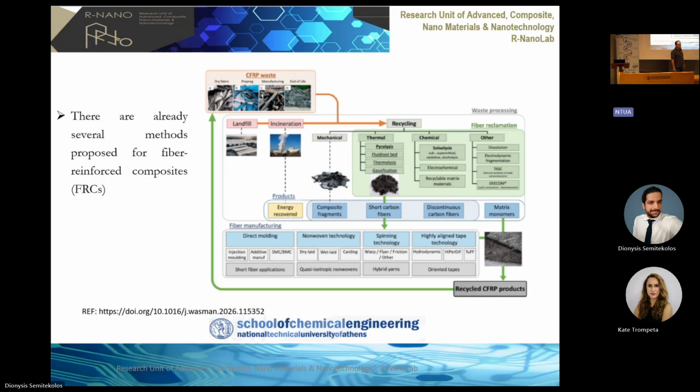Among thermal methods, the most well known is pyrolysis. When you have pyrolysis, what you do is burn out the organic material, which is the matrix, and you are left with the inorganic material, which typically is the reinforcing fiber, be it glass fiber or carbon fiber.